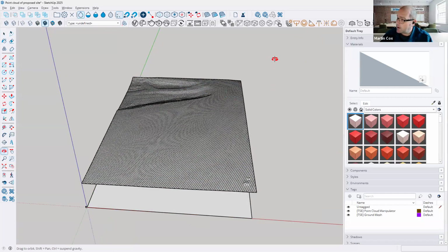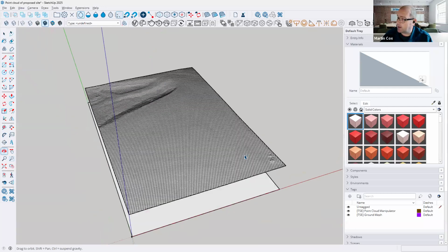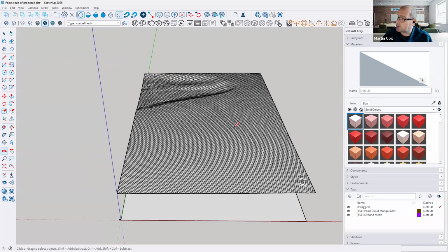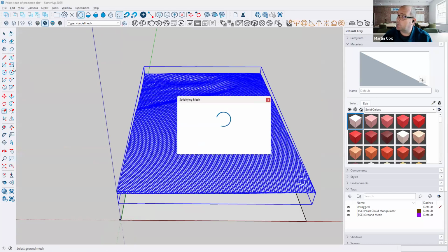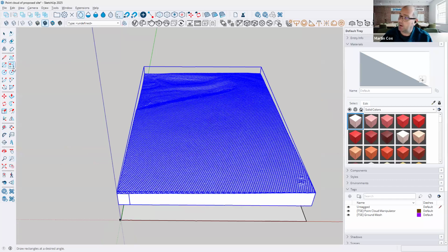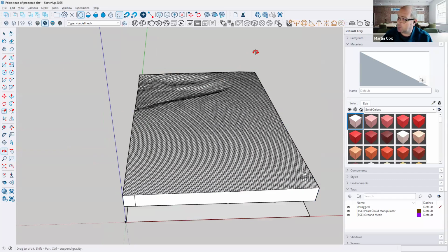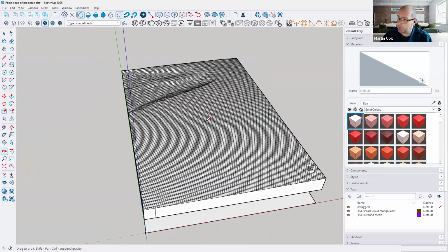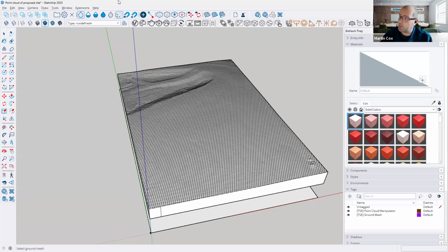Now, I mentioned I can turn off the point cloud. If I turn that off, here's my surface. This is a surface that I can now work with in SketchUp. And the great thing is I can also say, well, actually, I'd like to make this a solid. So this is taking that mesh and making it a solid within SketchUp. We now have that solid of that face using the point cloud. This opens up a lot of other tools, like some of the solid tools that we can actually subtract, using that cut and fill approach for landscaping. It really opens that up for us.